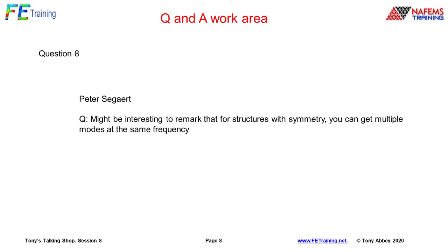What a repeated mode is really telling you is that we could have a response in the y direction, or let's say the z direction of our beam, and we don't know which direction it's going to go. So what the mathematics is showing us is two repeated roots, to say it's characteristically lateral and vertical out-of-plane response. You pick whatever direction you want if you're just doing a normal modes analysis. Basically, it doesn't know what direction to pick, so it gives you those repeated roots. It's a very interesting topic.